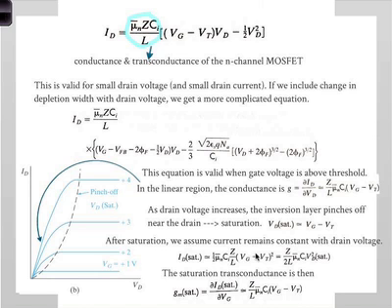But smaller, that's a good point. So that's one reason to go to smaller devices, right? You can get higher amplification in principle. Yes? Have it come out more to make the Z. Yes, that's a good point. It has two problems. One problem is that it takes more area, which means you get to put fewer transistors in, which turns out to be a problem. Second, you increase capacitance, parasitic capacitance this way, which we will talk about later.